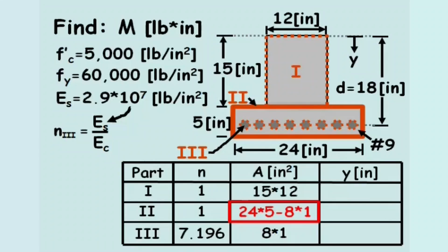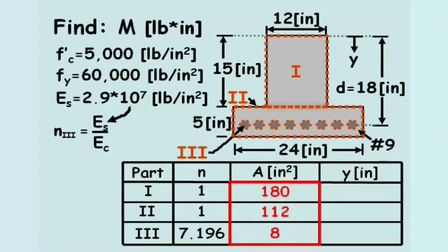Next, we'll simplify the area calculations. To simplify a future calculation, we'll pretend the area occupied by the rebar is occupied by concrete at its normal stiffness and also occupied by steel, except with a Young's modulus reduced by the Young's modulus of concrete.